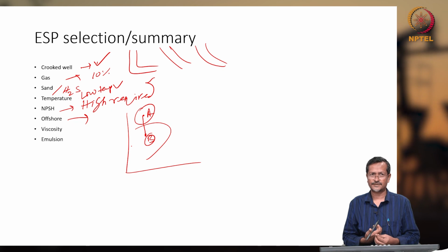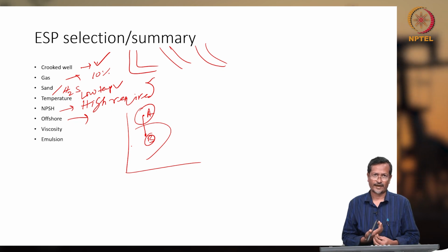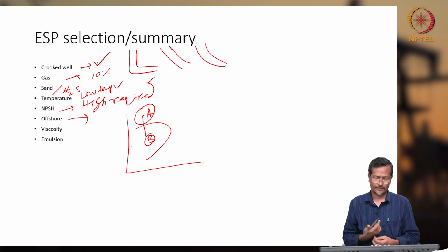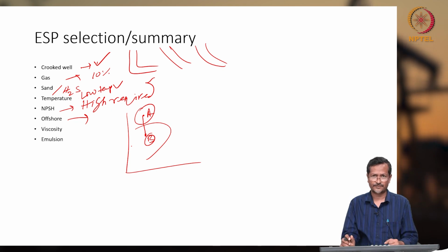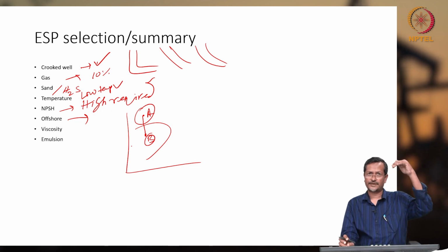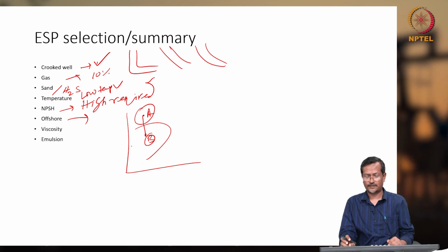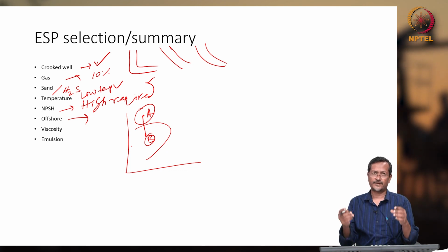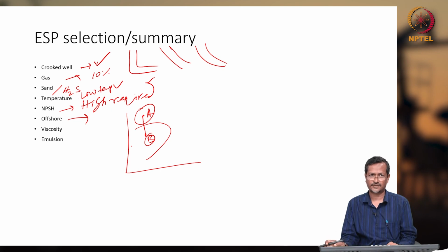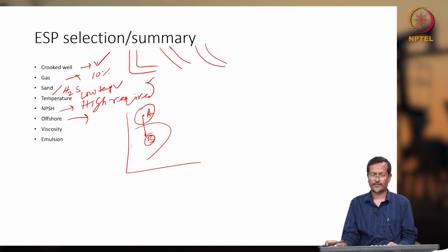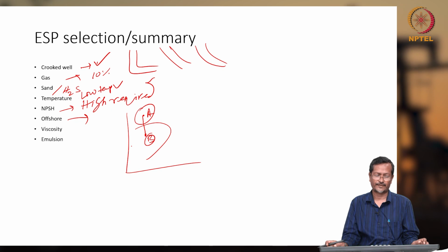So you have to use gas separator, but still there is risk of gas inside the impeller. Okay, especially the first stage is very important. If the first stage is getting gas, then the whole vibration will start. But in other stages, although gas will be there, pressure will be increasing gradually. So that pressure also will help to avoid it, or maybe it will give more mixture of things, and that will be less problematic. But the first few stages will be more problematic if you have gas.